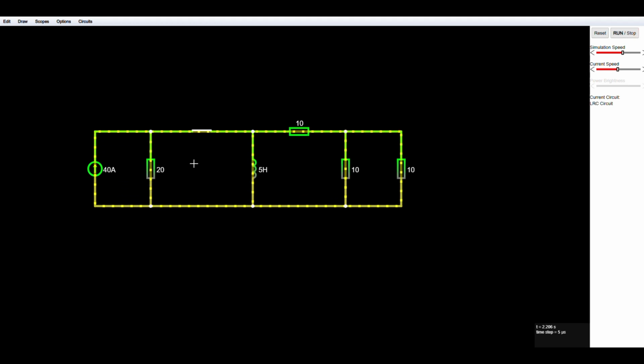So initially we have this type of circuit, and then let's open the switch. When I open the switch, now I disconnect this part of the circuit from that part of the circuit. So this part of the circuit does not have an external power supply or the independent current source. So basically the circuit gets its energy from the energy that is being stored within the inductor. This is what is known as the natural response. So that part of the circuit we don't really consider in our calculations. We just look at this part of the circuit after t is equal to 0.